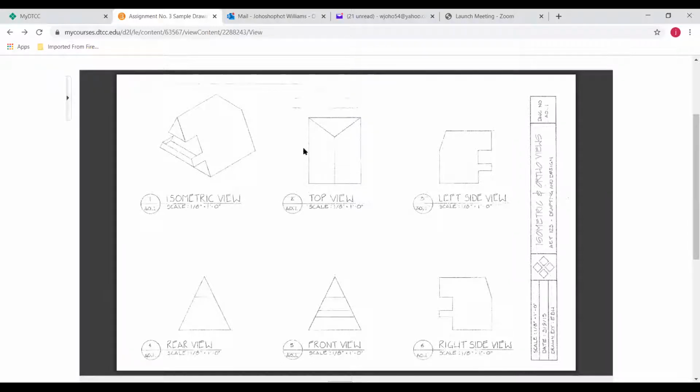And then we're going to do the top view, and then the right side. Whatever views you want to do next is really up to you. But I want to reiterate how these orthographic views are in alignment. If I project a line straight up this way, we see that the front view and the top view are in vertical alignment. And of course, these views here have the same horizontal plane.